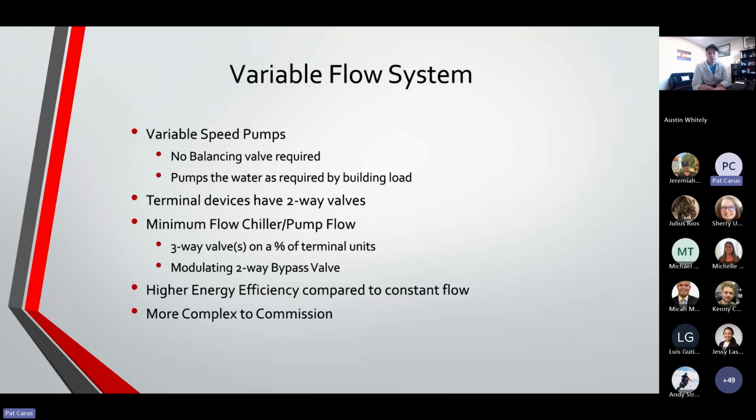The minimum flow of the chiller and the pump flow. One of the mistakes that we made in the early days was we didn't give you enough information as a customer about what that minimum flow was, and many times problems in the system were a result of not having enough flow to the machines. There is a minimum flow, and that has to be achieved. We've taken some steps, and I'll show you at the end, to make that easier for you to do.